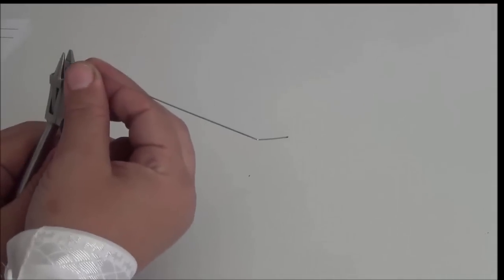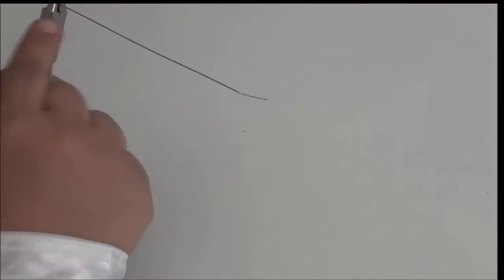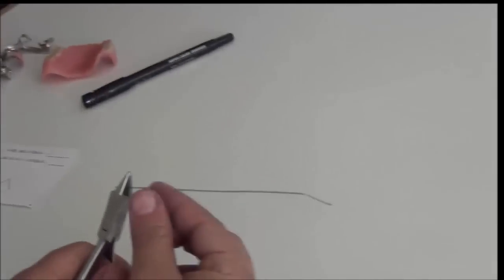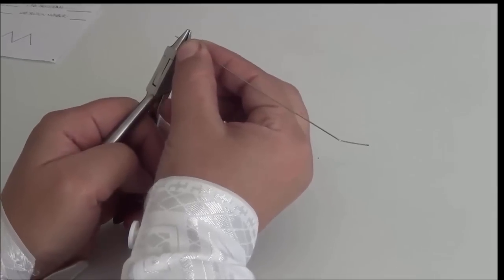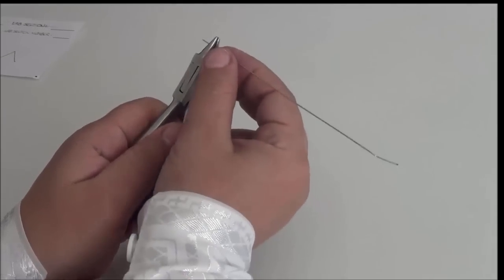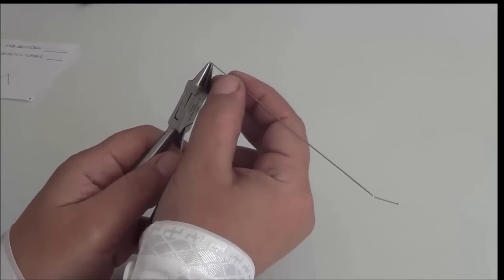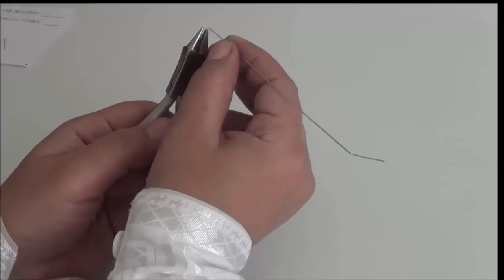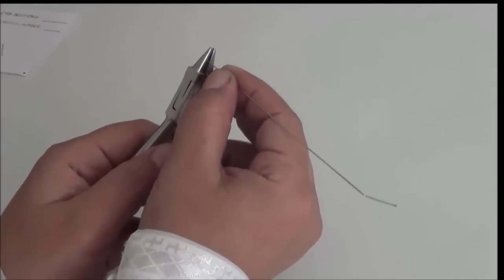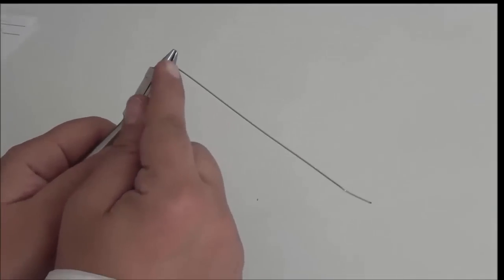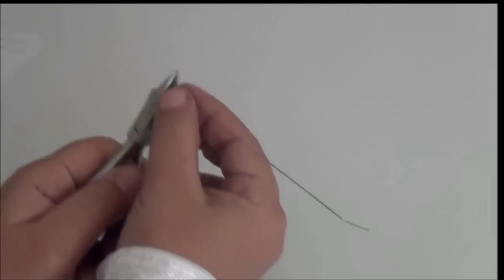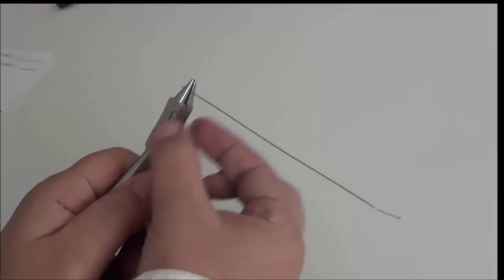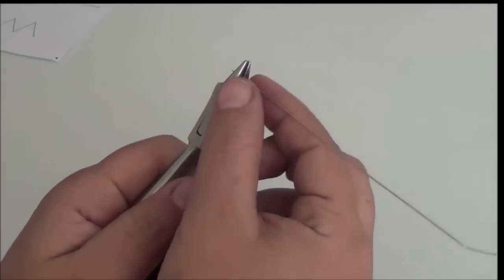So I hold the wire perpendicular to the pliers. Okay, so it's not like this. I don't bend like this, not like this. Sorry. It should be perpendicular. The second rule is that I should be away from the peaks. So I try not to bend in the last 2 to 3 millimeters of the pliers. I go closer to the middle because I need to make sure that the diameter of the wire is smaller than the diameter of the cross section of the peaks. So I don't want to ruin my pliers. The best strength I get is around the middle part.